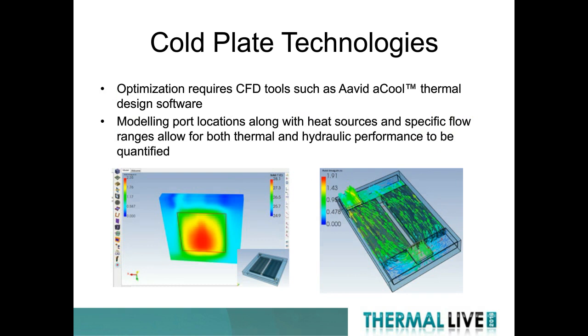What you see here are CFD outputs of the cold plate. Using CFD tools, at Avid we have our own code called ACOOL, and what we do is we model the fluid flow through the cold plate and the fin structures, and we pay special attention to the port inlet and outlet locations, because we have to not only look at the thermal performance, but also identify and model the hydraulic performance, because the hydraulics are just as important as the thermals.